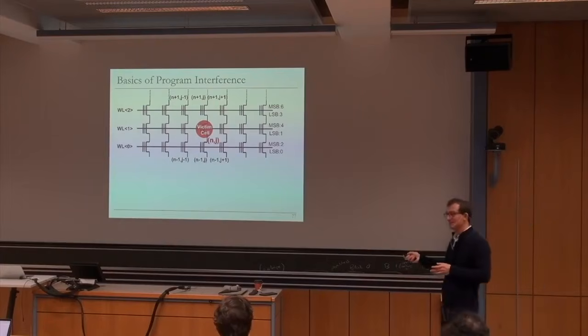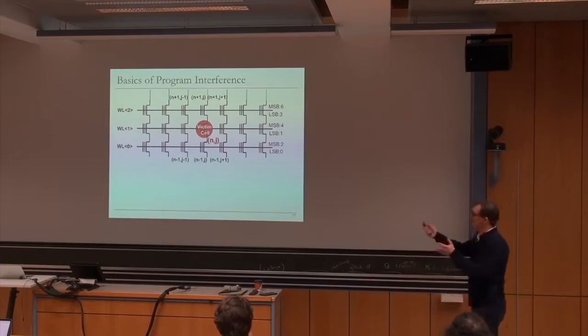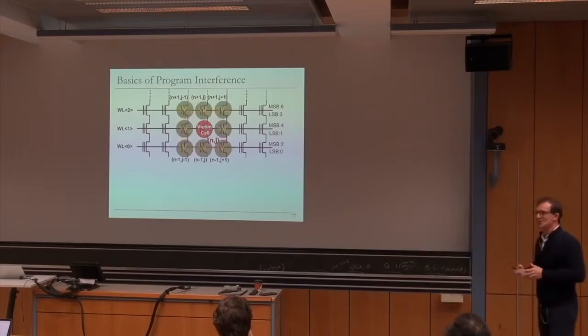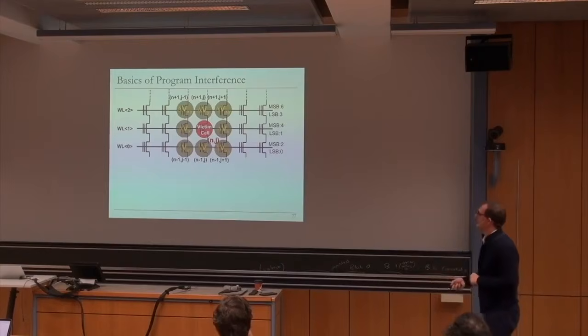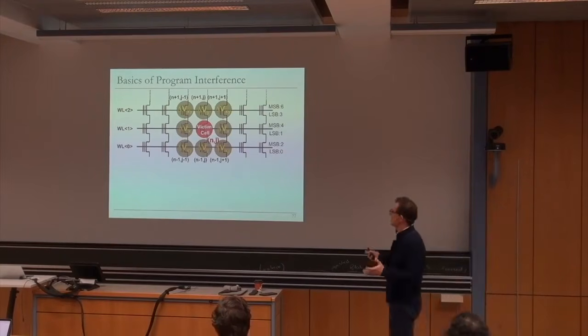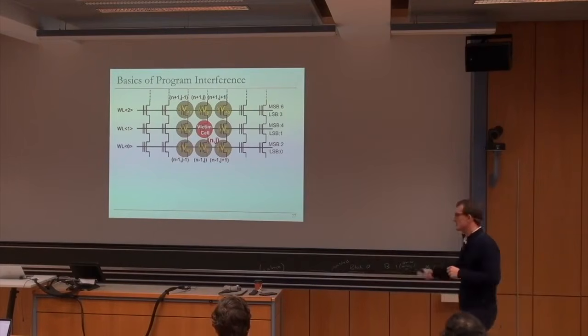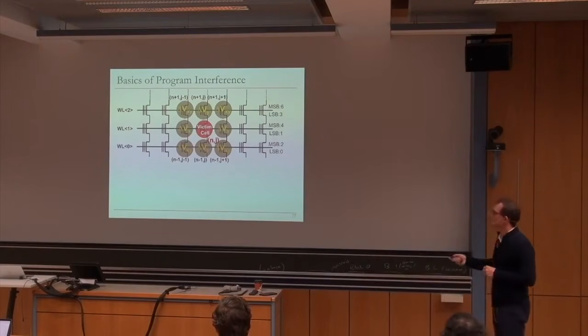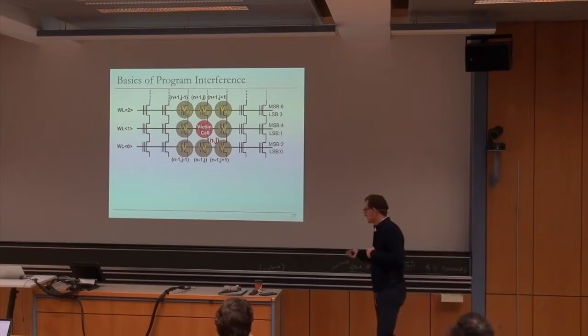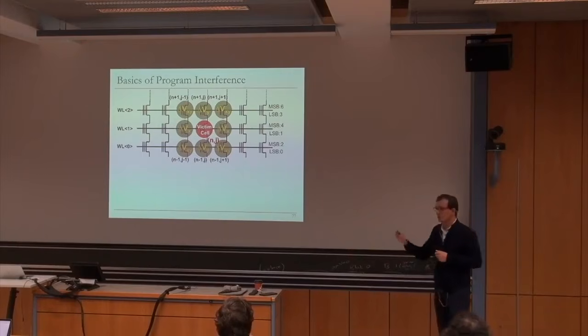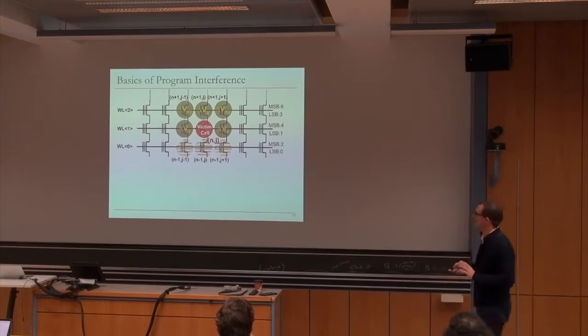You have a victim cell that gets affected by a lot of aggressors around it. And these aggressors are everywhere. Actually, all of these are aggressors, if you will. The good thing is, we want to look at how much each aggressor affects a cell. We're going to ignore this part because of the programming method that's used in flash memory. Usually, this gets programmed before this one. As a result, the programming of this word line doesn't affect the programming of this word line. Usually, the flash drive manufacturers program in an ordered way to minimize the effect of these interferences. So we're going to ignore these.